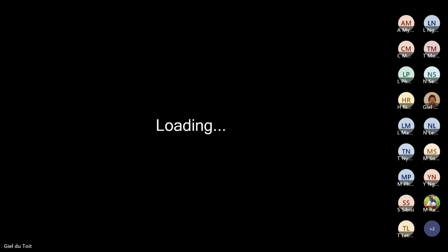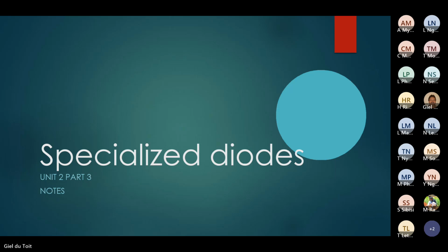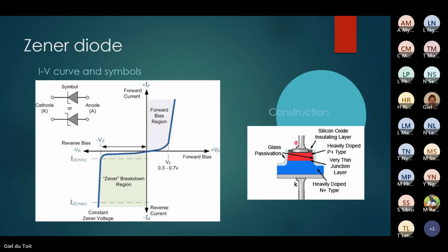Right, guys. This is now part 2 of the slides. So again, I just want to show you the diode when it's forward biased and reverse biased. We've got these two diodes. This is the anode on the triangular side, and the minus is that stripe there. You see that stripe? That's your minus. Let me use my laser pointer. That stripe there is the minus, or the cathode.